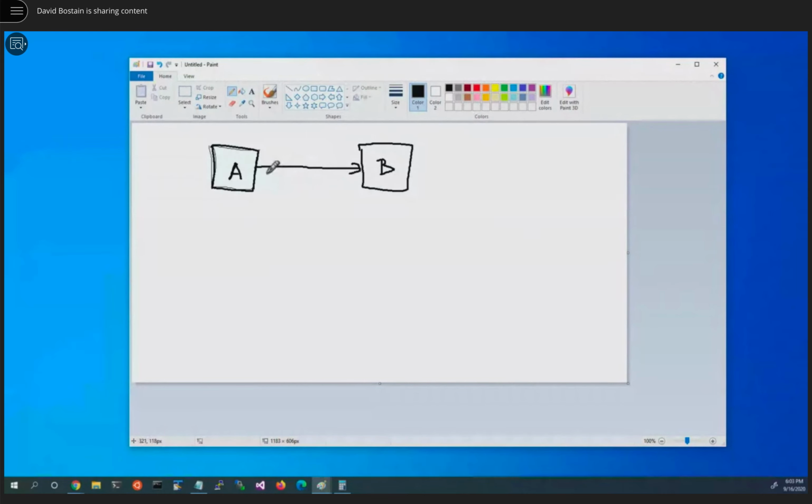Well, as you start to get lots and lots of events and states and signals you need to pass, this could become very large. Maybe this is 100 individual wires that have to go between point A and point B. And we call that type of communication parallel. Now, one of the advantages to it is that in parallel communications, things happen all at the same time. So these 100 events would be seen by B at the same moment, perhaps.